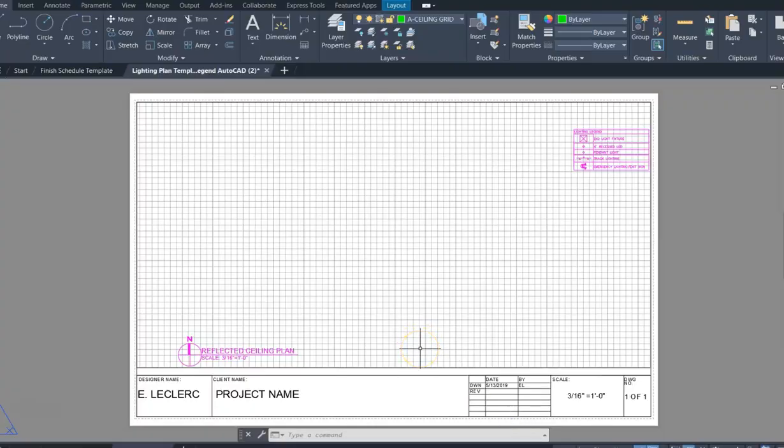You want to start by making sure that you provide enough lumens for each space. So remember to calculate that by getting the square footage of the room, multiplying it by the required foot candles. You can Google IES required foot candles.